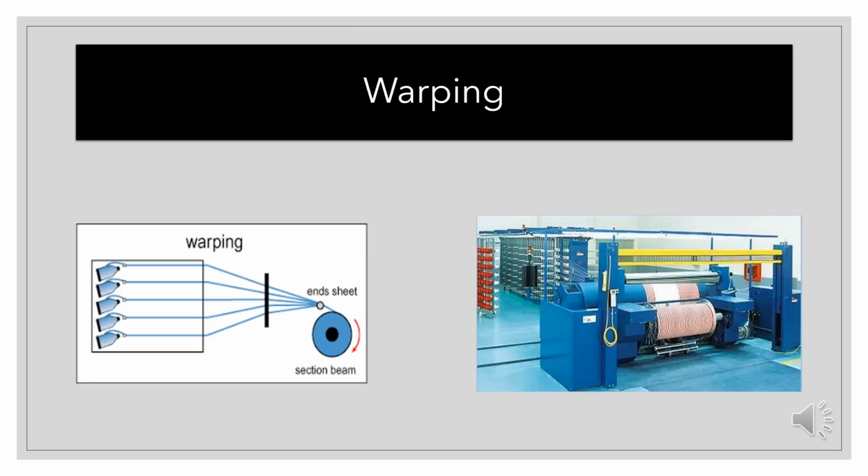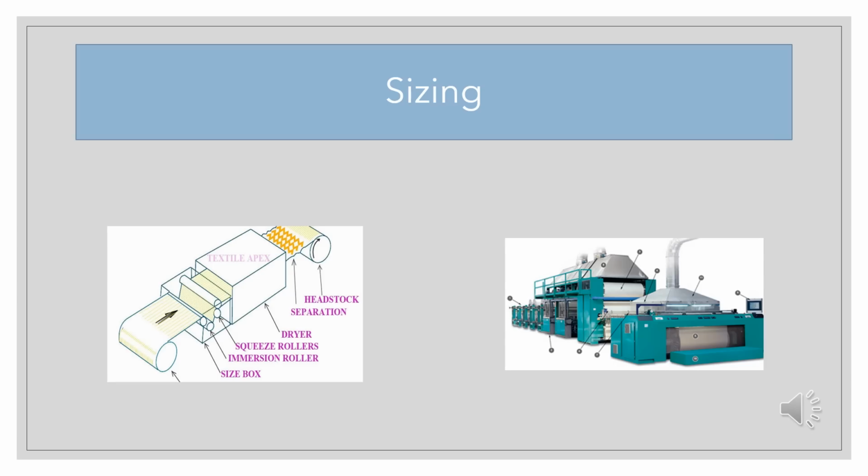The basic objective of warping is to build a package where yarn ends remain in uniformly set parallel and continuous form and thereby to accelerate weaving. Sizing. Sizing serves to strengthen the fine single yarns for weaving. Yarns are categorized into single and two-fold. The two-fold yarns are those composed of two or more threads twisted together, while single yarns are very delicate and difficult to weave. The warp threads are immersed in a bath containing the sizing agent which stiffens them. The yarns, once released from the drying room, are individually separated by large bars, so as not to create problems during weaving.